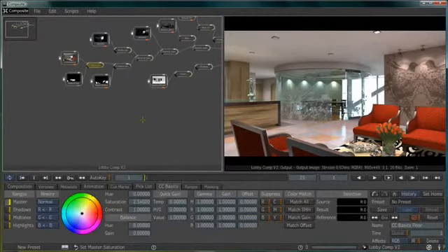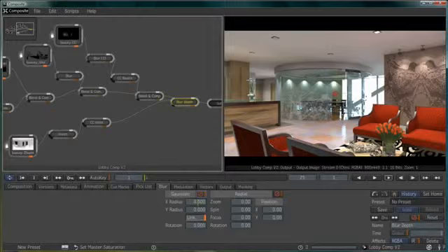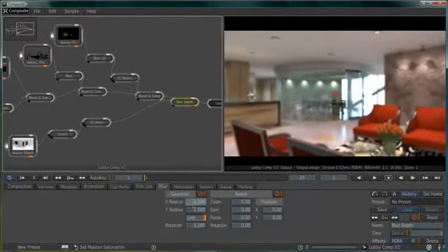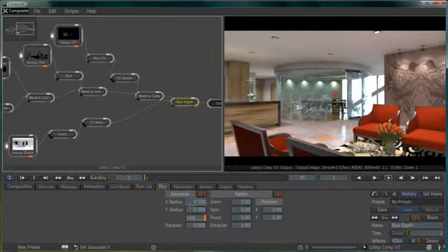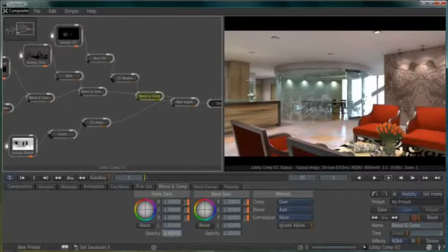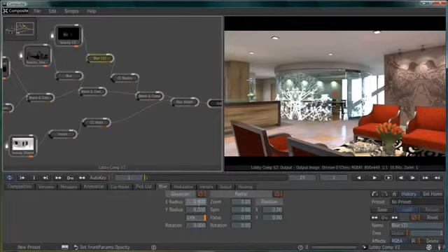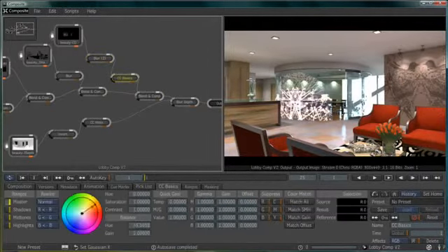the colors. Here, I will use the Z-depth layer from my beauty render and bring in a small blurriness on the back of my scene, adding realism and helping the viewer concentrate on the lobby area of this image. Same for the self-illuminated layer. I can decide to blur it a bit to bring some softness to the self-illuminated element or even change its colors.